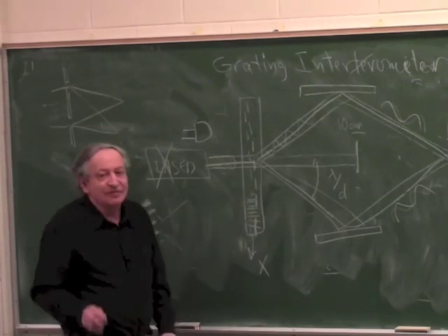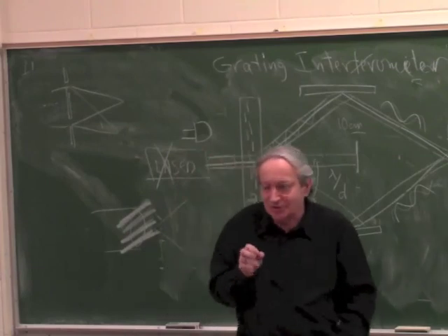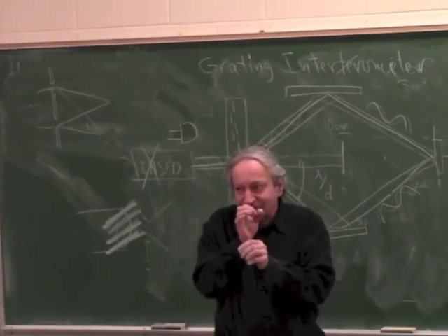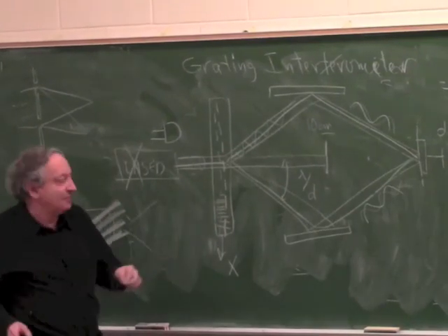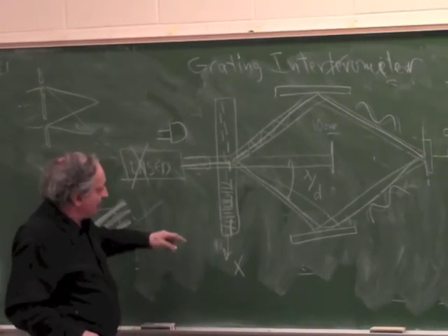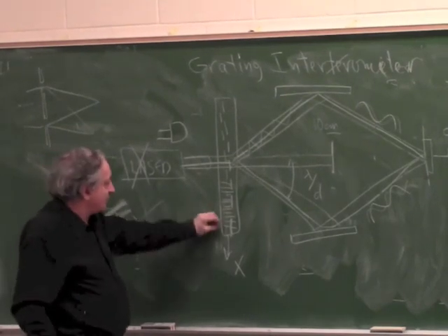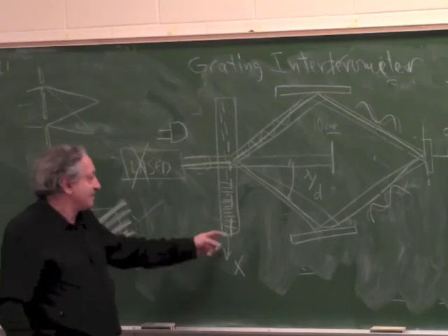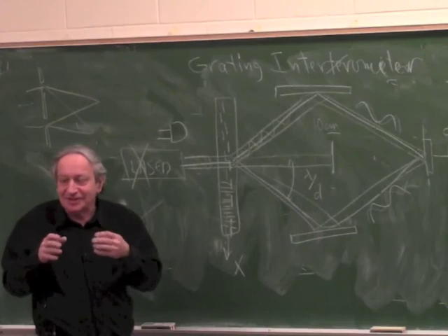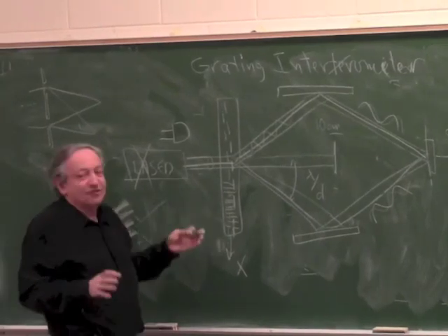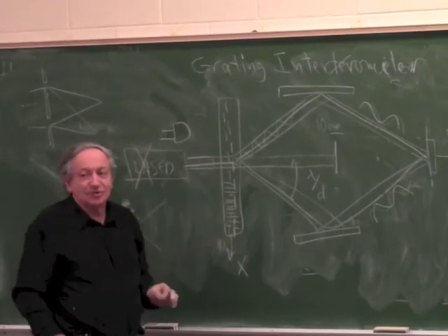And typically when you make a very fine grating with a traditional encoder, you have problems because you have to resolve the lines. Basically what I'm comparing this to is a linear encoder with the same fine grating where I want to read the line position directly. But if I want to read the line position directly with a microscope, the finer the lines, the harder to read. I have focus problems. Here I don't need to focus anything. If the light source moves, if this moves, it makes no difference.